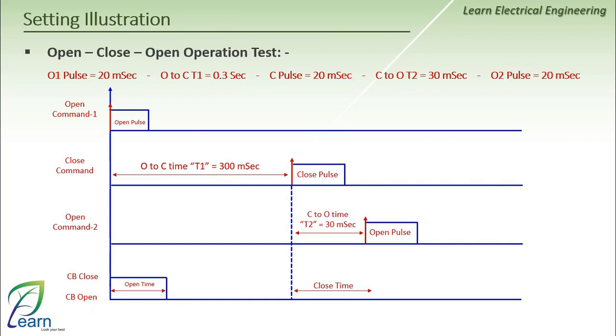In this case, the breaker is supposed to open again after the main poles close, and we must ensure something very important during the test. You might find the open time to be about 10 milliseconds longer. Why is this? Because, as we saw in the circuit breaker video, the trip spring must be charged during the mechanical movement of the circuit breaker while it is closing. And this is, of course, through the discharging that occurs to the circuit breaker's close spring. So naturally, you have inertia that you want to overcome while charging, and then it happens.